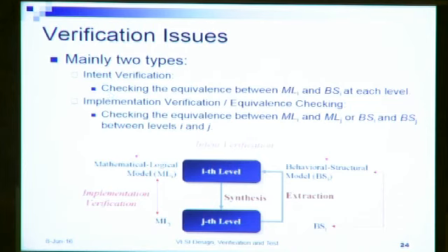Intent verification tries to verify whether whatever I have in the behavioral structural model at the ith level correctly incorporates all the requirements of the specification that I have. So I will mathematically and logically model the specification, which will incorporate within it all the properties that the design needs to satisfy, and then we will verify that all the properties, all the timing properties, say reliability properties, functional properties, are correct with respect to this mathematical or logical specification.